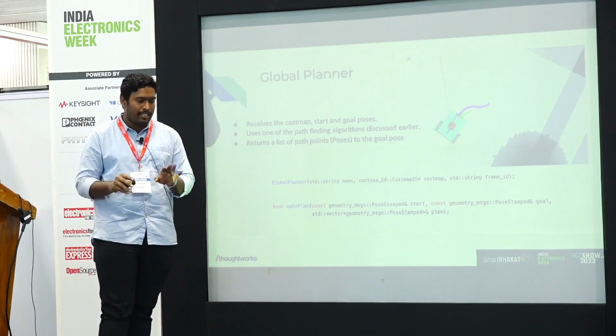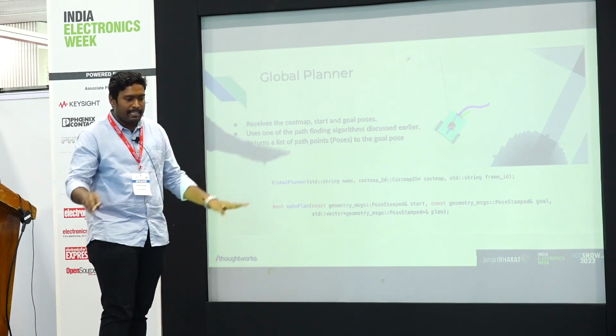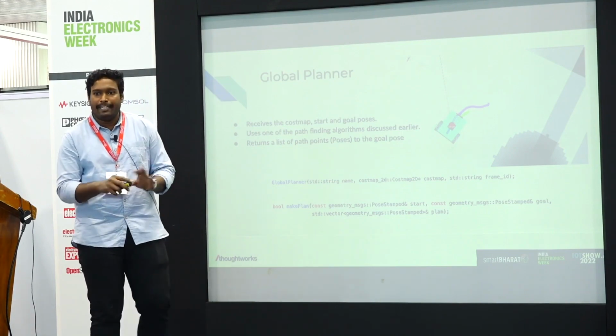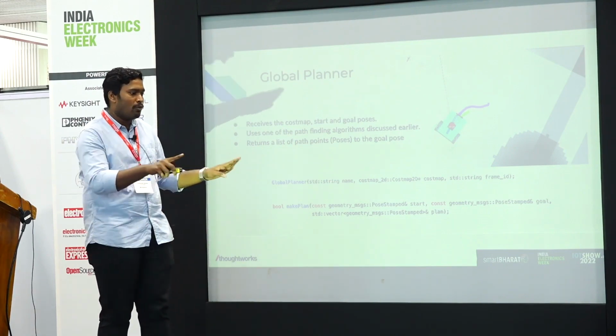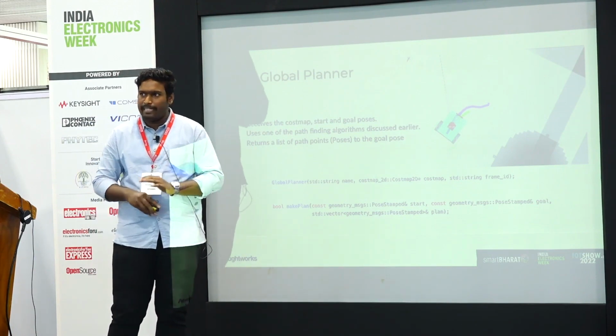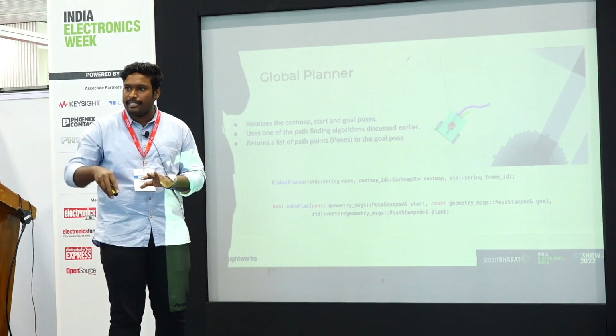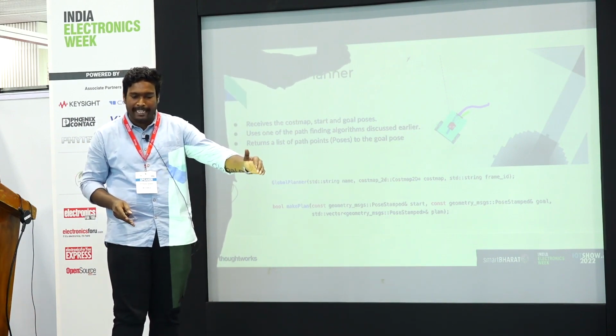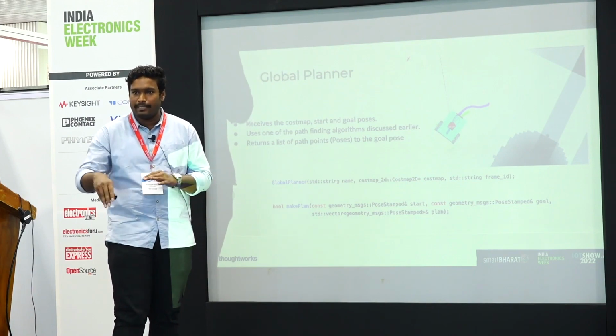If it is a differential drive bot of size, let's say, 1 foot by 1 foot, then it's going to cover 4 meters. It's not going to create a plan for the entire global plan that was generated. It's going to consider only a small amount of area, and it's going to navigate in that place.